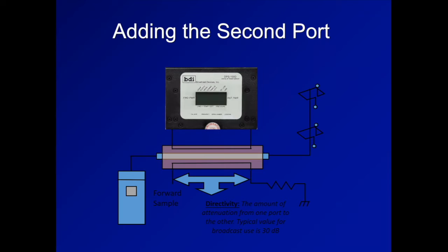So that's going to have not quite the greatest isolation. And let's use 10 kilowatts forward power, since that's a nice round number. So let's just assume an antenna return loss of 22 dB, which will return about 63 watts.